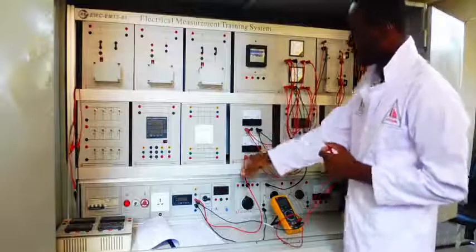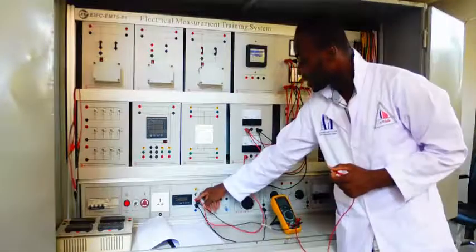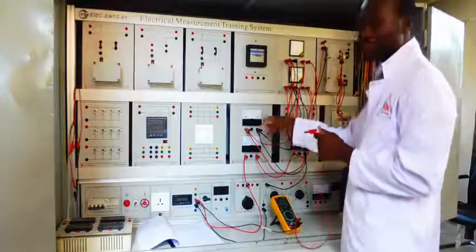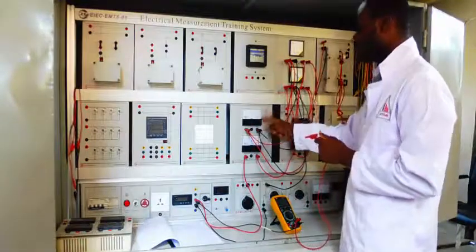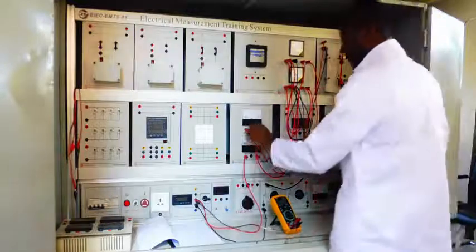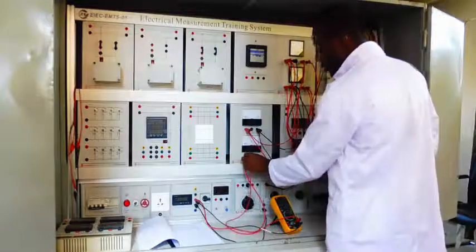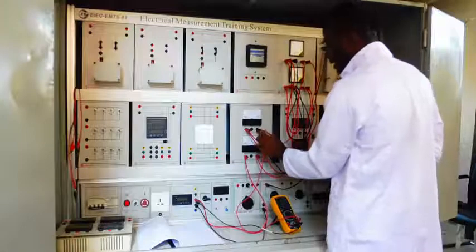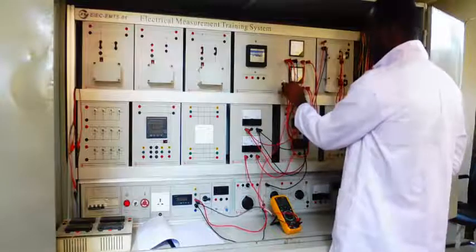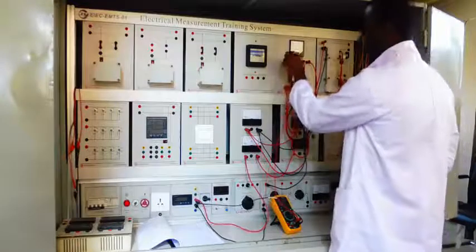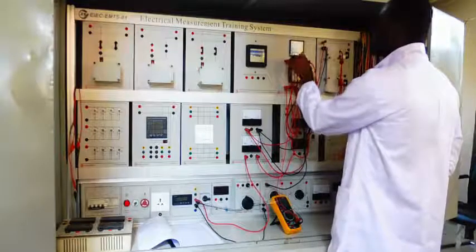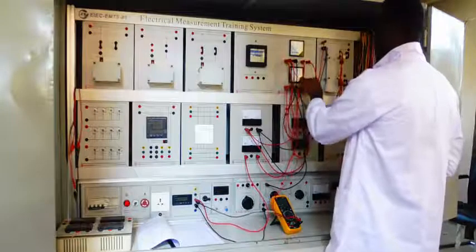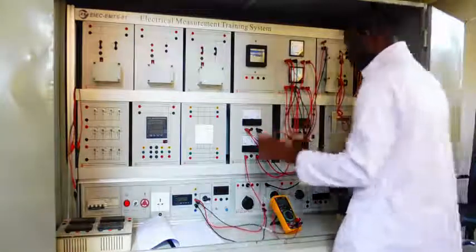I will place one probe at the red one, then use the other one to test it. If the red has a connection with the black one, then the light has a connection with the neutral. So only the red wire cable will show continuity, but when you check the black, it won't. If it doesn't, then it means that the light and neutral don't have any connection with each other. So the red is going to be optional.